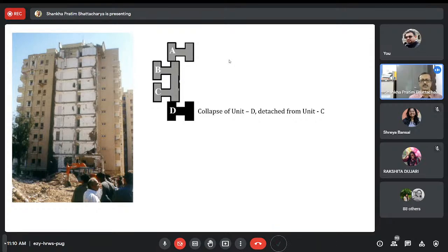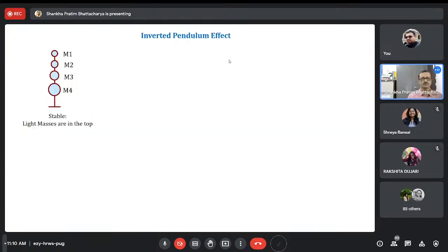The two wings of D, like an H, will behave differently at the time of an earthquake. So as far as possible, avoid the asymmetrical scenario. Go with a symmetrical plan and a balanced way.